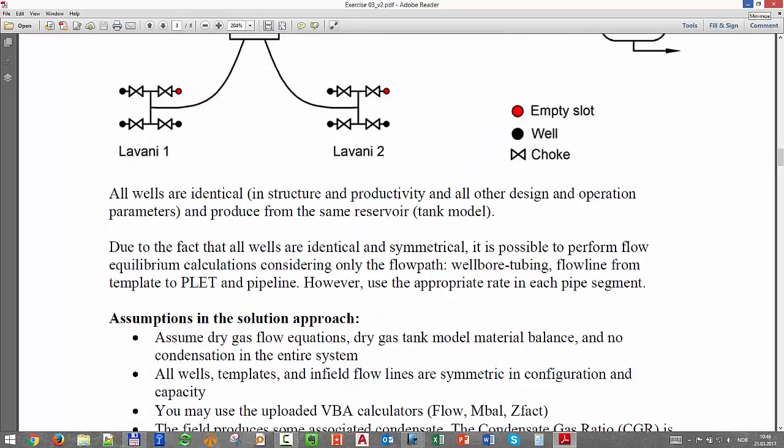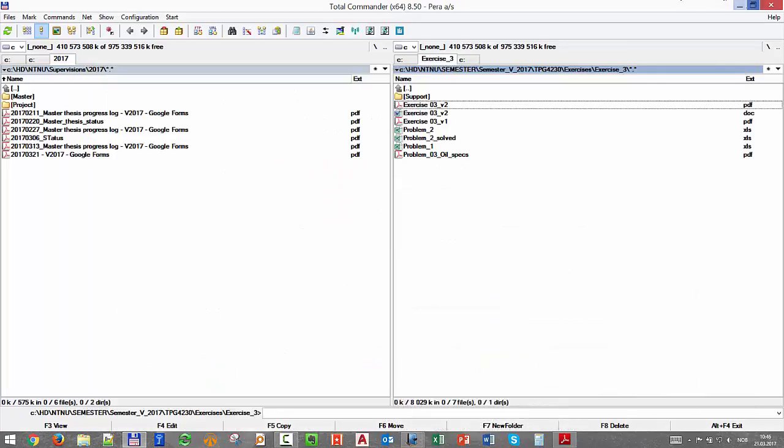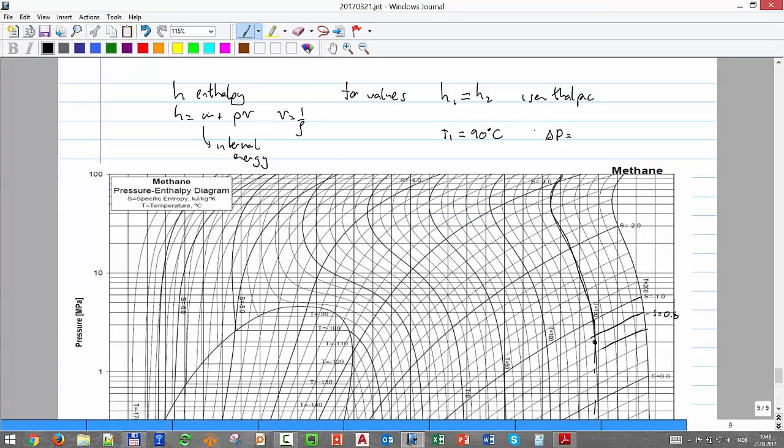Yeah, exercise 1. You have your Excel sheet where you have performed your calculations in time, of the plateau, the production profile. What is the wellhead pressure at time 0, for the first moment of production? Pressure 1, that's one, right? Wellhead pressure is 343 bars. 43 bar.